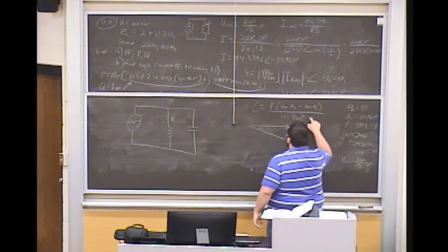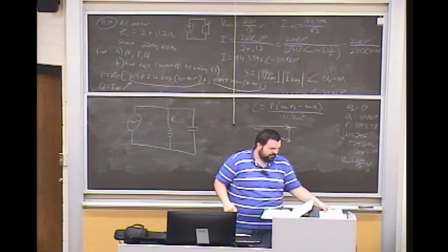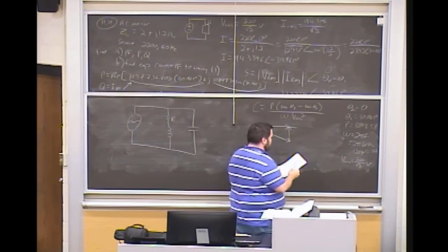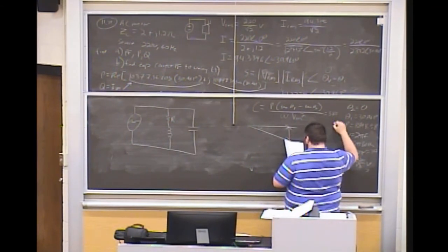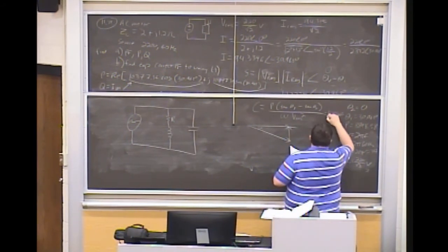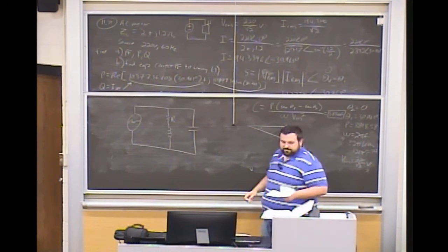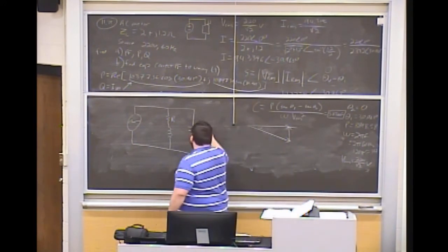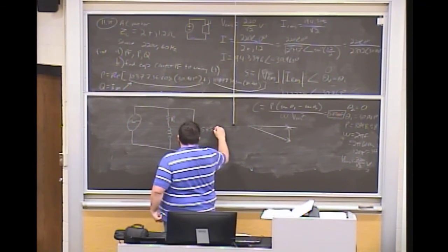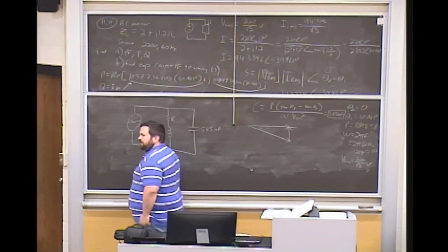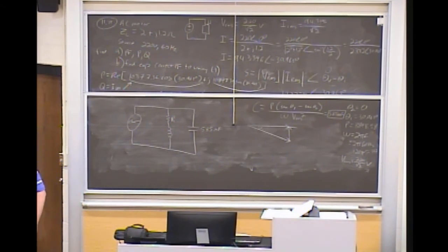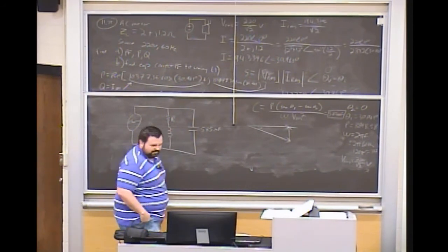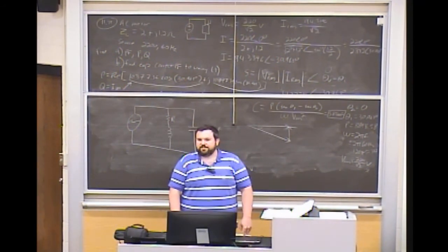And so if you plug all of those values into that formula, it works out to 585 microfarad. And so that would be the capacitor you would pick to put out there. Any questions on that? So that was kind of my semi-high speed hour and 11-minute journey through chapter 11 problems.